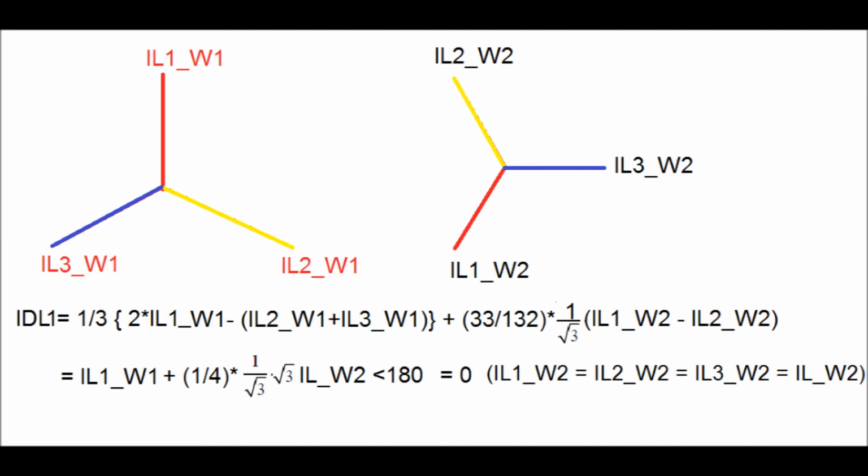This is how the differential current for the ABB make RET 650 is calculated. Similarly for the red phase, yellow phase and blue phase windings, IDL2 and IDL3 come as 0. But in actual, a slight differential current exists due to CT error, and also due to tap changing, that is the different tap positions in the OLTC.